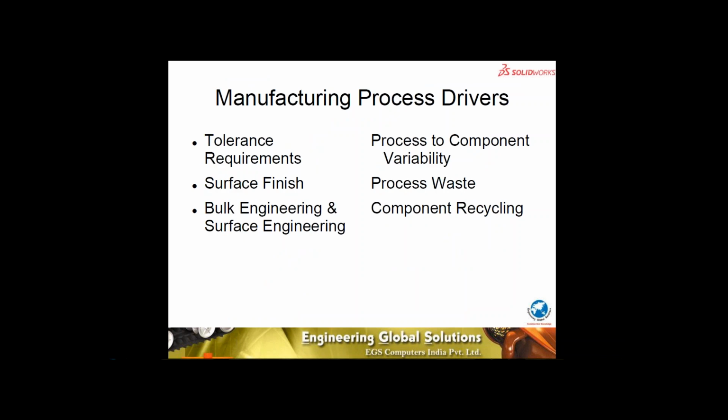The manufacturing process drivers in addition to these are the tolerance requirements, the surface finish requirement as dictated by the fit, form and functional requirements, the bulk engineering and surface engineering requirements, the process to component variability, the wastages that accrue in a process, and the component recycling or the waste recycling.